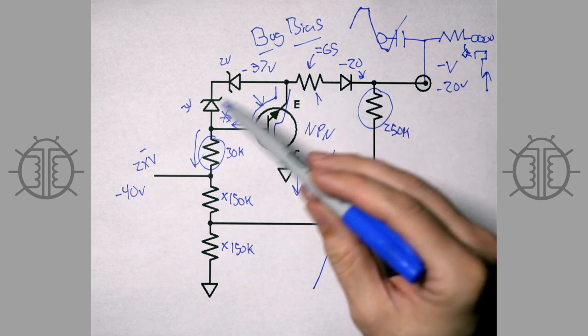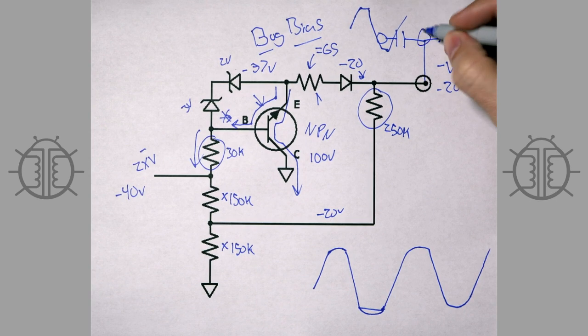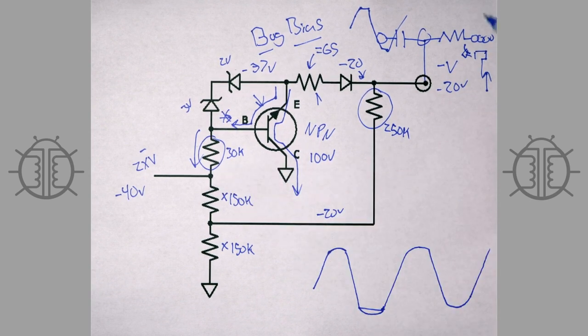If you do this properly, it completely eliminates crossover distortion, and if you put your multimeter right here, if you measure it, and you clip the amp, this will not move. This voltage, the average voltage, will stay the same. The output tubes will not turn off. They will stay on, and all is well. And the cool thing about this circuit is it drops right in.